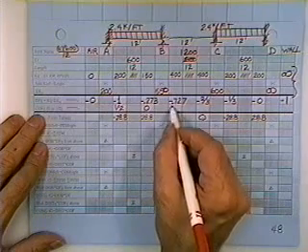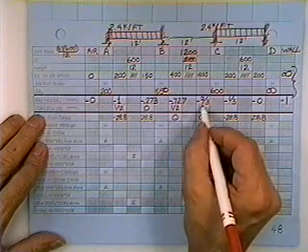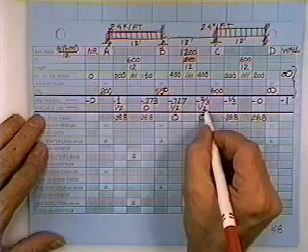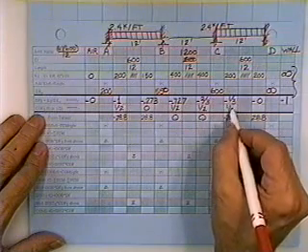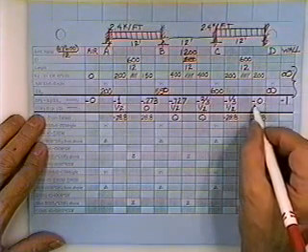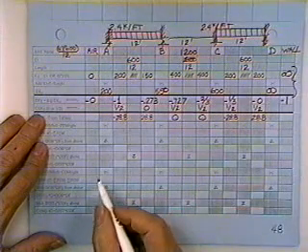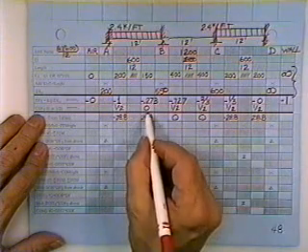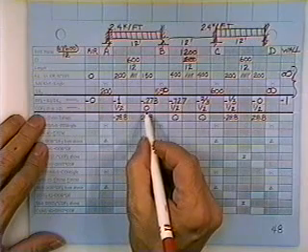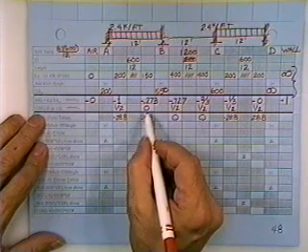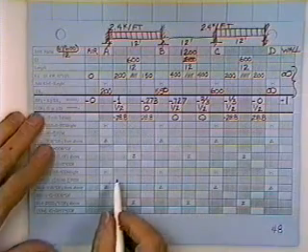I stand at B and look at C, a half. I stand at C and look at B, a half. I stand at C and look at D, a half. I stand at D and look at C, a half. I mean, it's almost always a half. The only time it's not a half is at B when you look down there and see a pin. There is no carryover factor on that one.